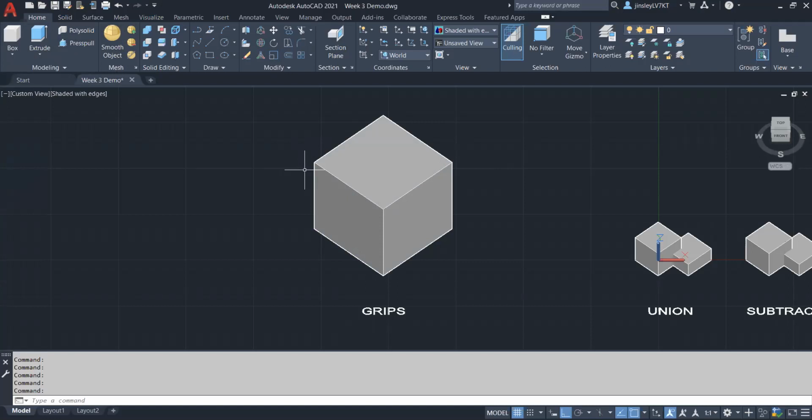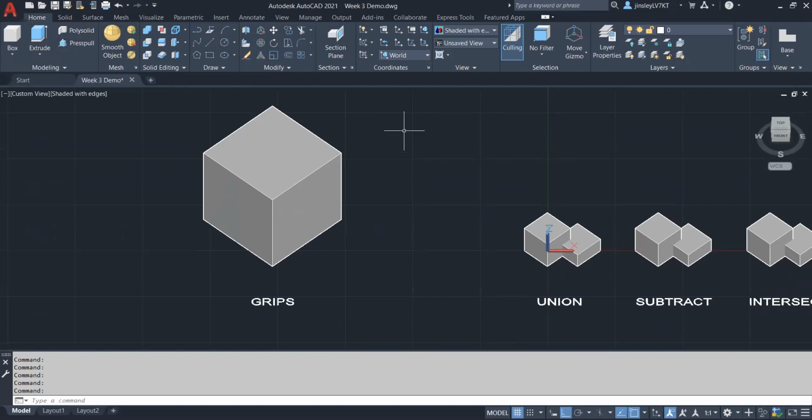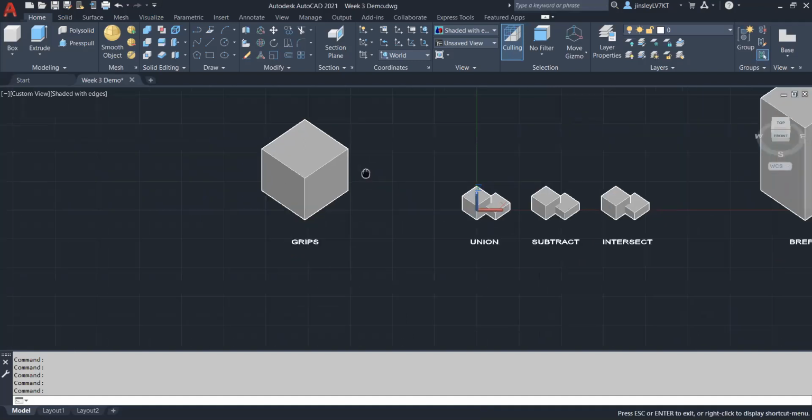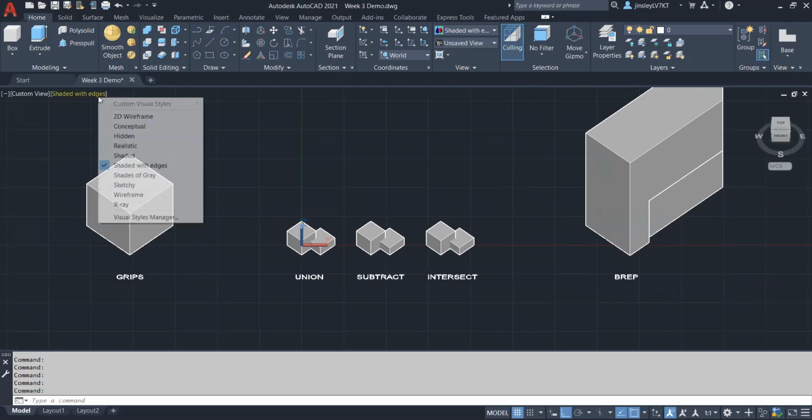On my work computer, even on this laptop, I have 16 gigabytes of RAM, right? This whole file, when we're working in 3D, has to fit in that 16 gigabytes of RAM when we process it. So as you begin to create your model, if you start looking at it in a shaded view where we're actually putting colors to the surfaces, that memory will slowly be used by your file. And eventually, if you model enough things or you model something that's too complex, you can actually crash the file, right?